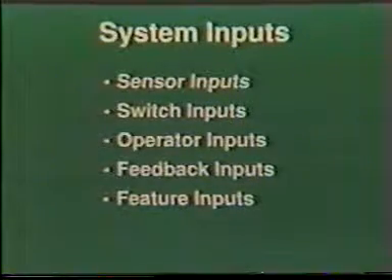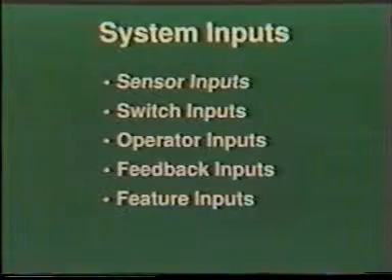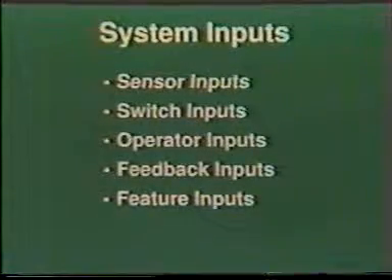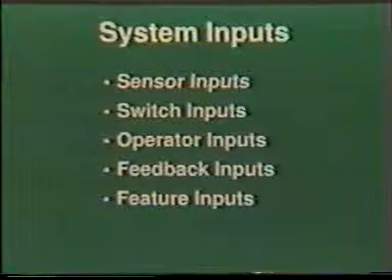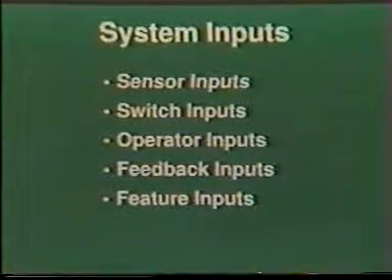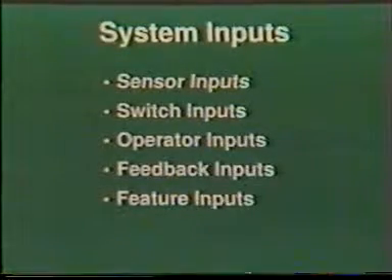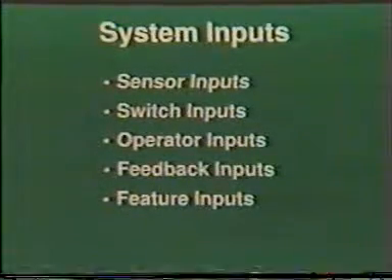The ECM utilizes input information to determine engine, fuel, and timing pressures, or more simply, to operate the engine. The inputs are divided into the following: sensor inputs, switch inputs, operator inputs, feedback inputs, and possible feature inputs.